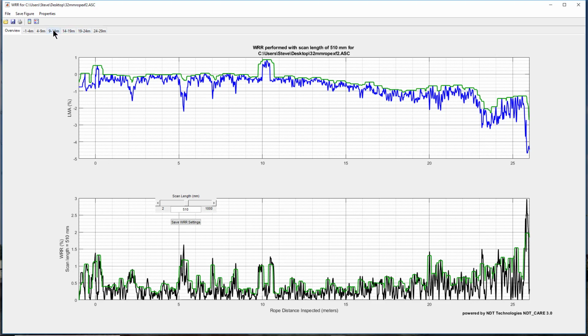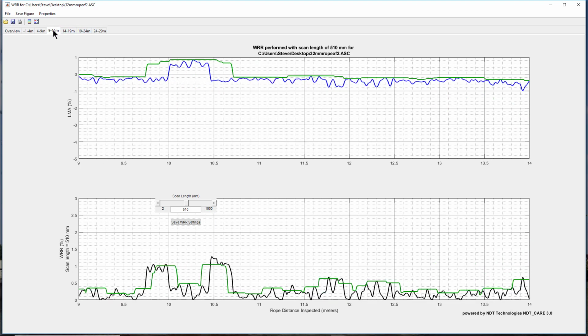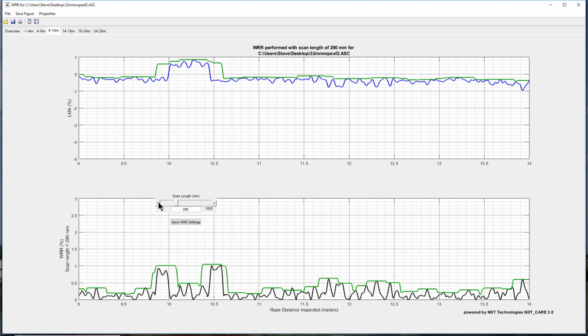You can also go to various tabs. I'll click this tab. Notice this still appears. I could also enter a value. Maybe I want 300, and I'll hit enter. Notice the charts update to 300 millimeters on this axis and also in the title. You can also use the two ends, click, to get some adjustments as well. And in this case, we'll go by 10 millimeter increments. So any of those ways you can do it.